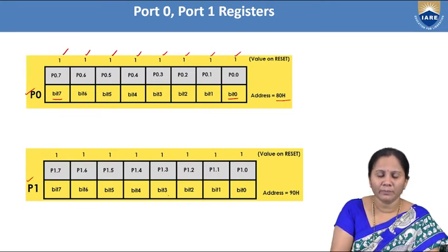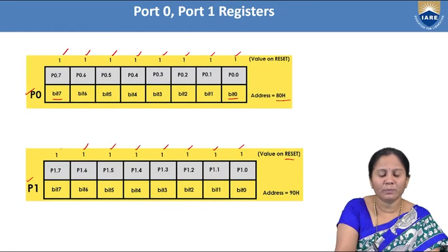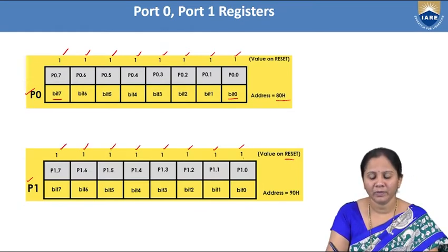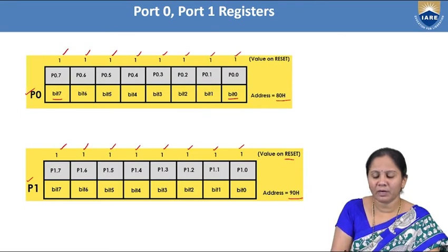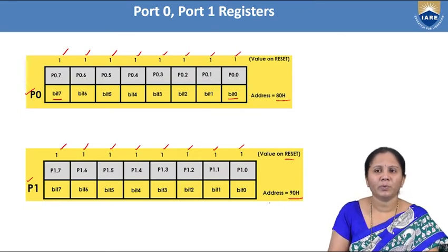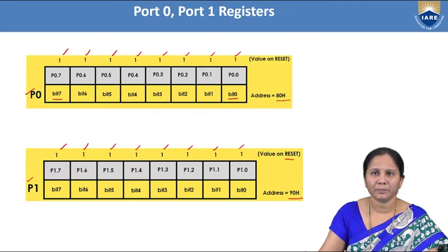For port 1, when it is reset, all the port bits will be set to 1. The port bits will be used as input ports, and the fixed address in the SFR address space for port 1 is 90H.